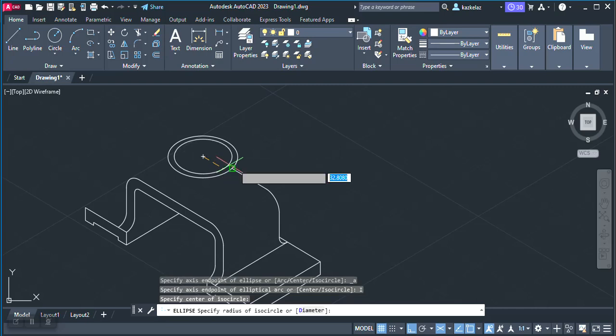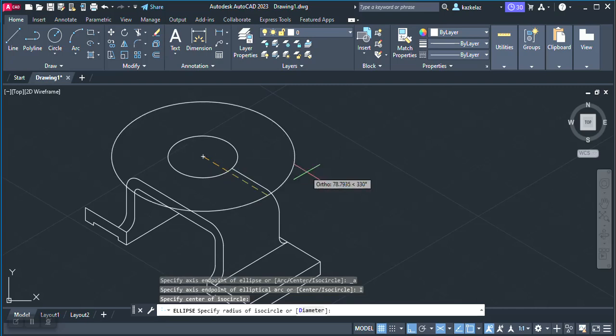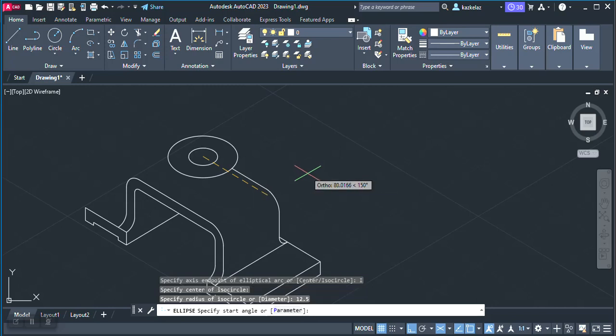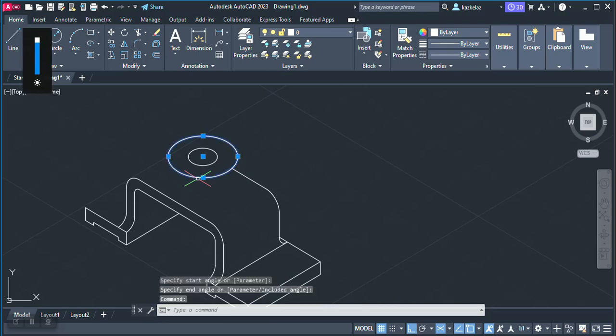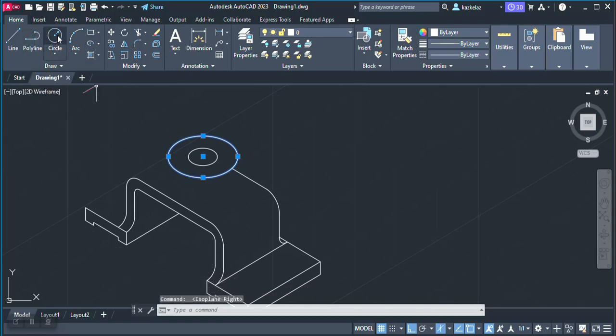Let's select that circle. We know that we're going to also have that same circle 28 below that one. So we have this circle, that roof first. We have to go 28 down for us to get that circle. So we have these two circles. We're going to join using quadrant, right?